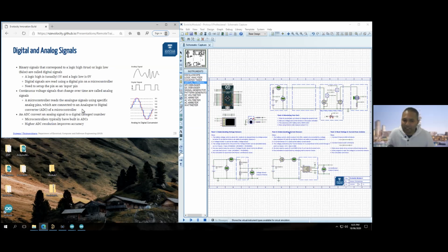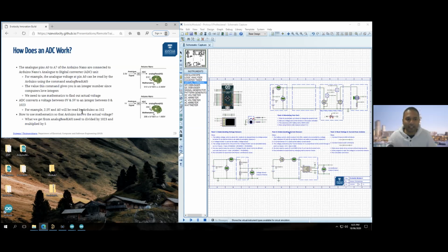You can count from 0 all the way up to 1023 by having 10 different ones and zeros. That means if you get a 0 voltage signal into the analog to digital converter, or the ADC, that will be represented as a 0 number. And if you get 5 volts, it will be registered as 1023. Any number in between would be scaled based on these numbers. Okay, so it's just rounded to the closest one. Closest possible, yeah. So there would be some error.